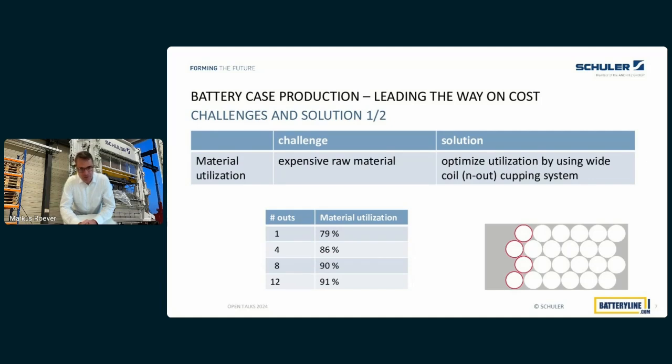And this is really a big portion. If you go from 1 hour to 8 hours, you already gain 11% in utilization. In the example, material was 50% of the product cost. That means 11% translates into 4.5% cost down for your can price. Okay, next please.